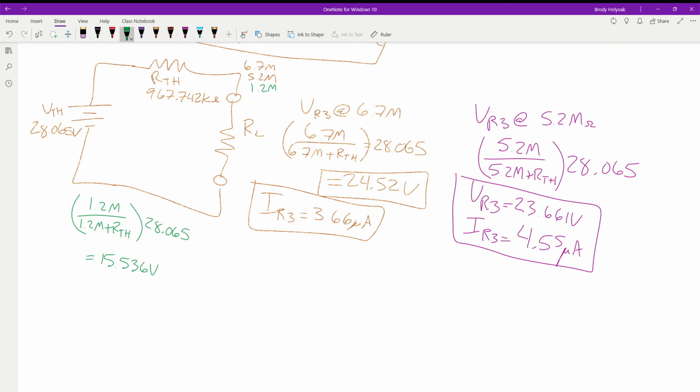So that's what I was saying, is use your guesstimates. You guys have a good enough understanding of what is going on that when you're just getting these values, do they actually make sense? Should I be getting that? So looking back at this guy, you can think, okay, I've got almost a meg here. I'm shooting at just a little over a meg. They should be fairly even, and they should split this value pretty close to in half.